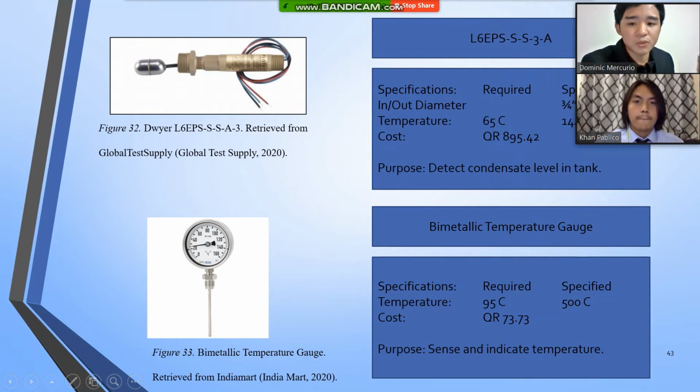Now, the pump that was selected in this project has a larger volumetric flow, and since that would cause an even faster rate of depleting the water inside the tank, this sensor will be responsible to turn it off when it reaches the minimum amount of volume.